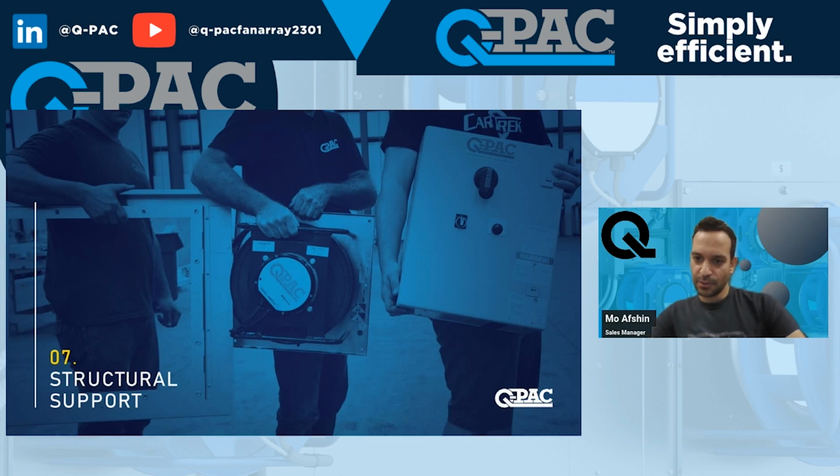I think there's a question on FEG: does it not include the loss of a motor? Yes, exactly. FEG does not include the loss of a motor, but FEI does. So I think that's a very good step from the code in the right direction, to show the actual efficiency of a system.